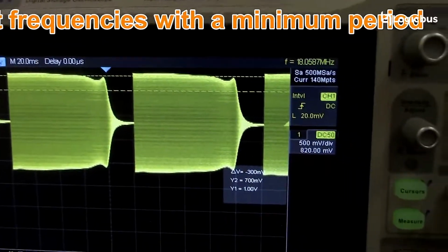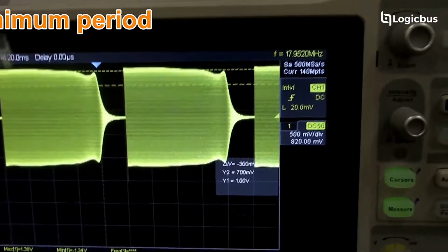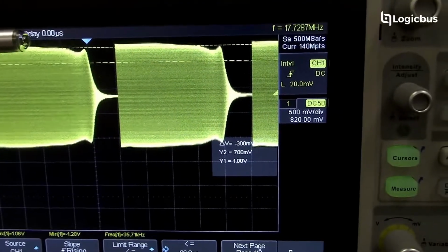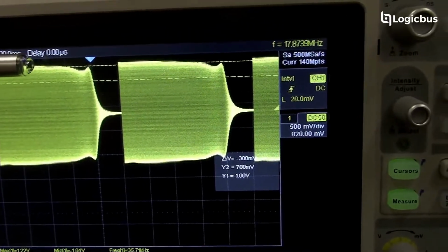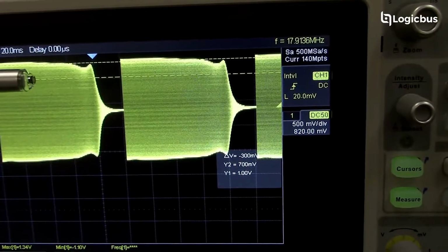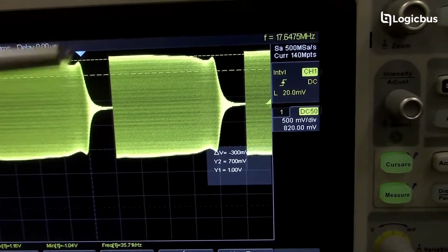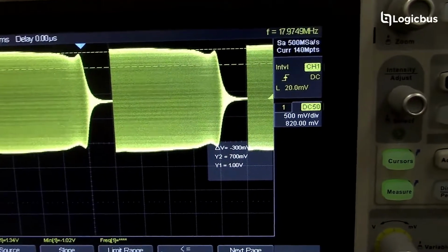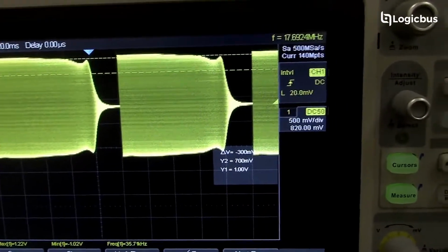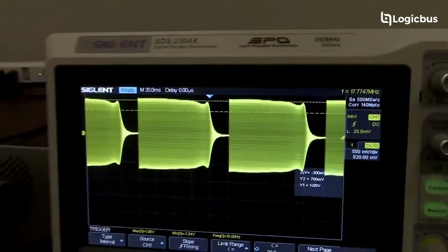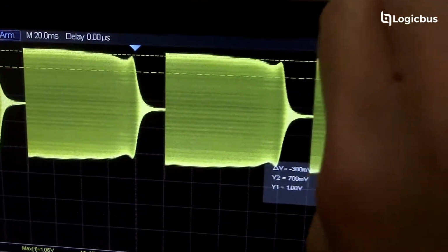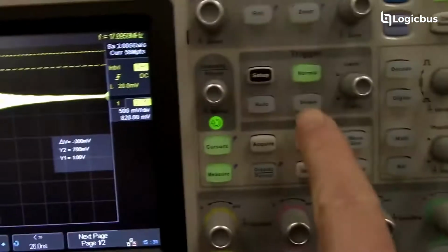And what you can do now, I tend to put the instrument into single mode once I've captured it. So basically, we set channel 1 to the maximum VPP level. Then we want to go 3 dB below that point and then align this trigger location. It's going to zoom around the center, so we can't really see much as far as the frequency here. But now what I will do is zoom in on that area.